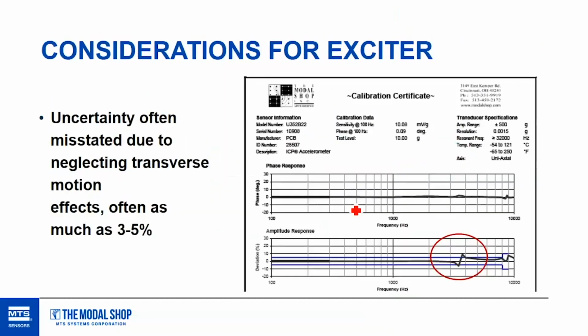So in your cal reports, you'd often see stuff like this. You'd see a little blip, drops down, and then it pops back up, and then it kind of settles back into normal. And what's happening here, again, 1,000, 2,000, 3,000, 3,500 hertz, you get this little blip in your cal result. And it depends really on the density of the points that you're testing as to what the shape of that is going to look like. So if you land right on that frequency, you'll have a very high output potentially. Or if you skip that frequency entirely, this could look like a flat line. So the density of your test points can affect whether you see that or not.